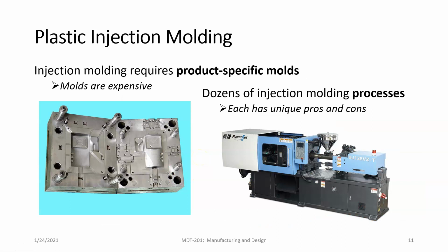So what does a plastic injection molding machine look like? Well, it looks like this machine on the right-hand side. All right. So we have a ram or screw thread here that's going to inject. This hopper has the plastic, the pellets. The hopper is going to distribute the pellets into the screw thread here where it's heated. The screw thread is then going to force the plastic into this area behind this chamber, and this is where we have our dies.